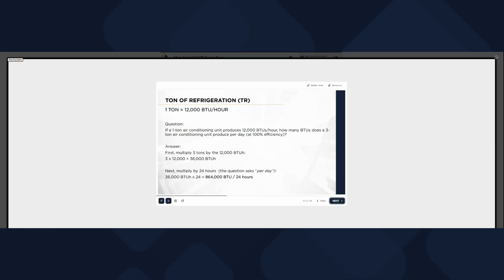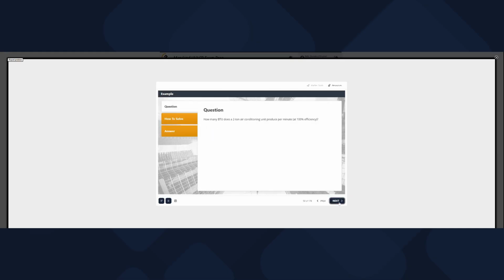Next, multiply by 24 hours because the question asks per day. 36,000 BTUH times 24 equals 864,000 BTU per 24 hours, or 864,000 BTU per day. Let's work through another example. Click the next button or on each tab to see how to solve and the correct answer.